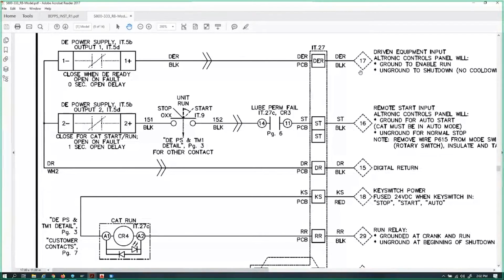I'm not sure if we did a digital enunciator class, but we talked about digital channels on a DE3000, or discrete channels, sometimes referred to as normally open, normally closed channels. In those cases, we said one terminal, let's pick on channel 10, was producing 5 volts. The other terminal for channel 10 was looking for 5 volts.